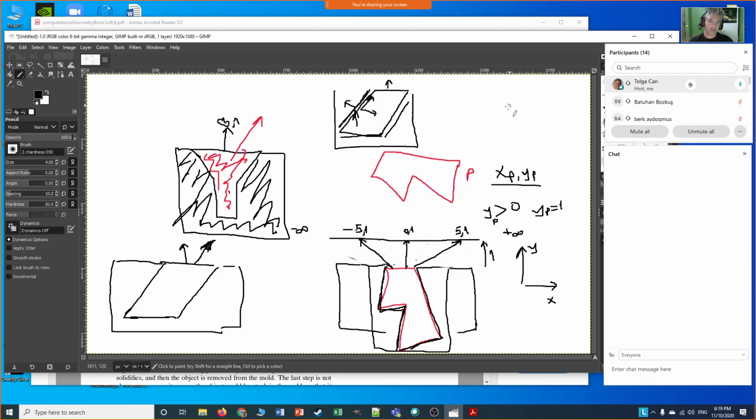By the way, the question we are trying to answer, given a polygon, is: is it possible to design a mold for it so that without breaking the mold, you can pull the plastic outside the mold with just one pulling action? All right. For example, it's impossible to create a shape that is like a sphere. You cannot have a single mold.